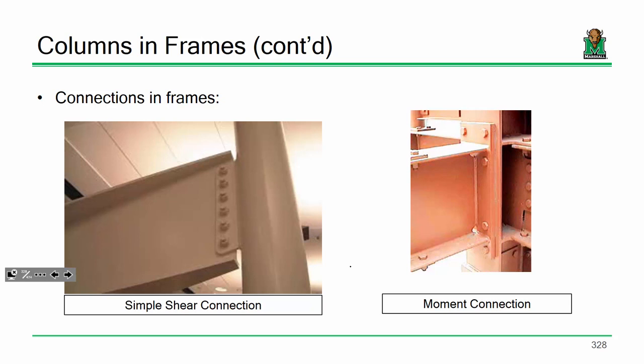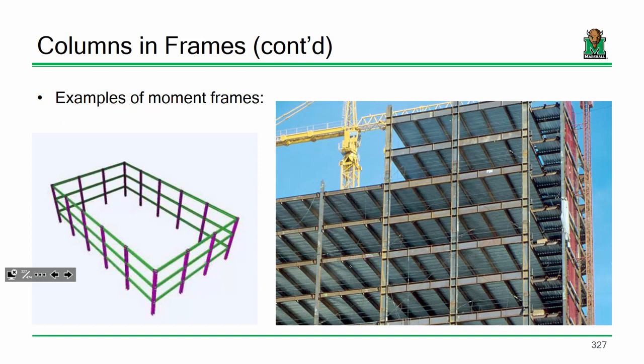See, in this moment connection, we're not only connecting the web, we're connecting the flanges as well. It's the flanges that are transmitting that moment. And it's not just the beam that you have to deal with. Look at this. Look at these columns, okay? And look at these columns. See these plates here and here? Everybody see that? Well, if I bend this beam, think about bending moments, I've got a large sort of concentrated